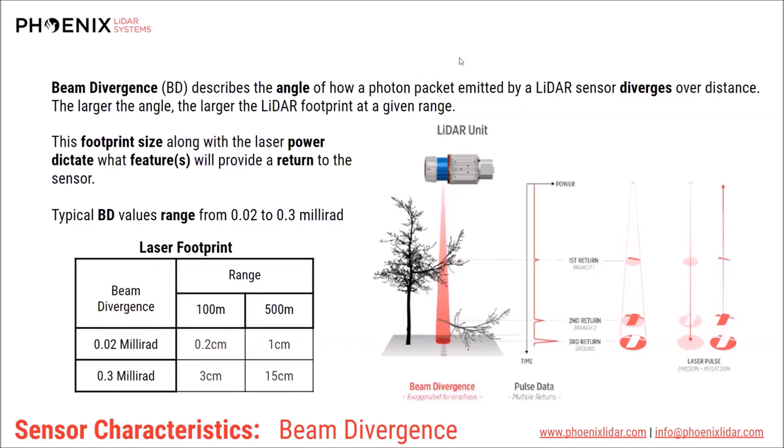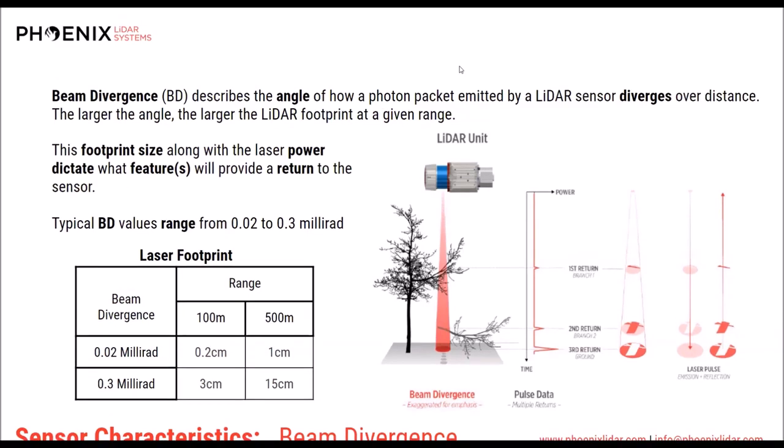Great. Okay. Well, thank you very much. Our second question is asking about the difference between the VUX1 UAV and the VUX1 LR. That would be our Ranger UAV product and our Ranger LR product. Other than the differences in pulse repetition rate, I think the UAV has a maximum PRR of 500,000 pulses, and the LR has 750,000 pulses, if I'm not mistaken. That is, they're both 1350 nanometer laser systems, and they're both single laser systems. What is your experience with being on the post-processing side and having worked with data from both sensors? What are your experiences with the differences between the two?